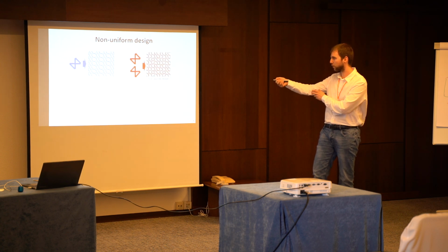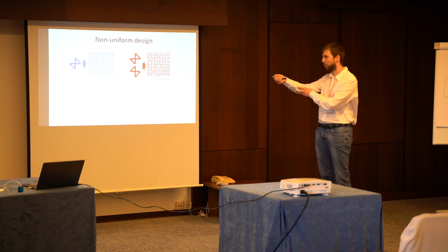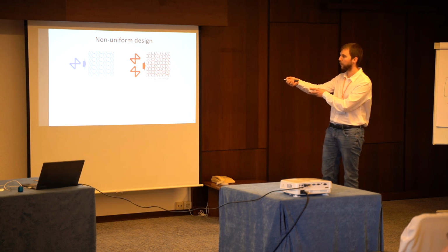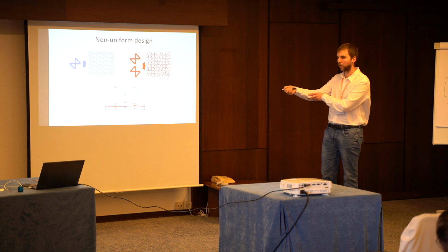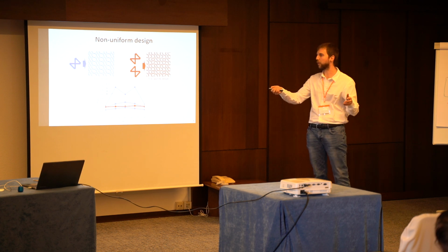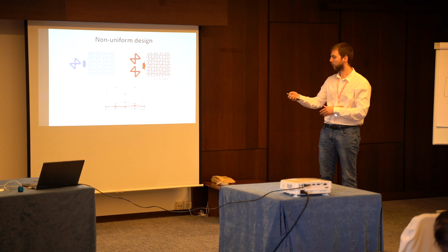While if you consider the same building block combined with its 90 degree rotated version, you obtain a more complex pattern, and the effect of this long wave phenomena is somehow eliminated. This is confirmed by looking at the buckling strength as a function of the loading angle. We are compressing these structures, and they're going to buckle, and for different loading directions, we obtain these curves.